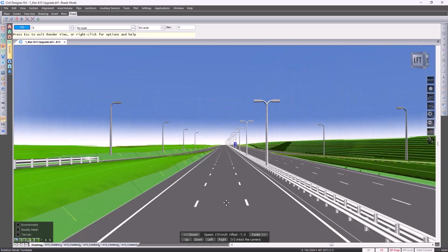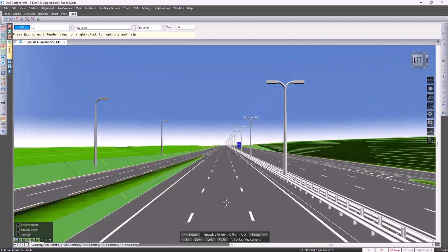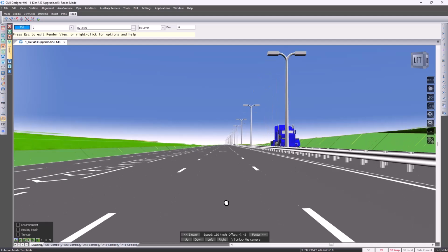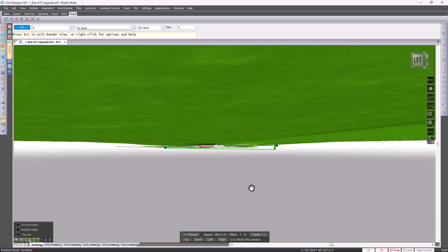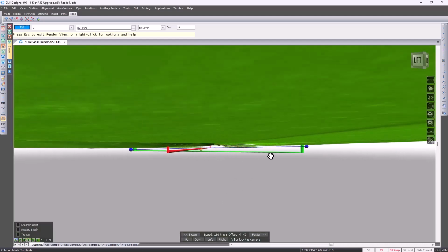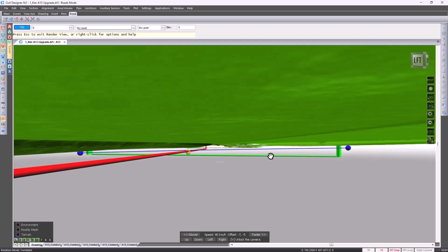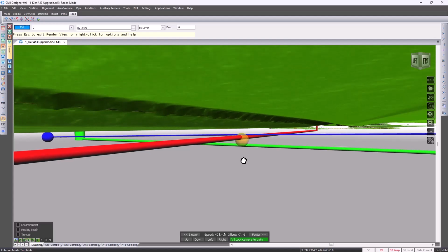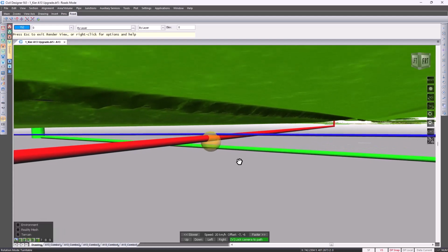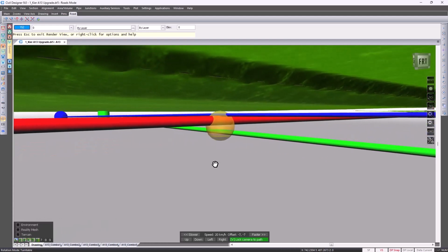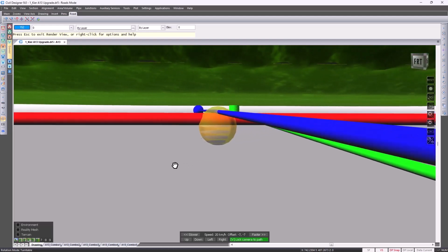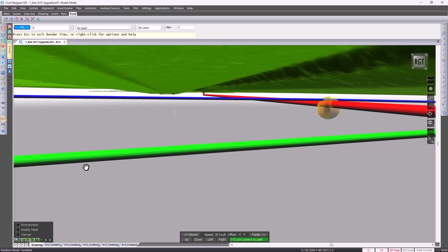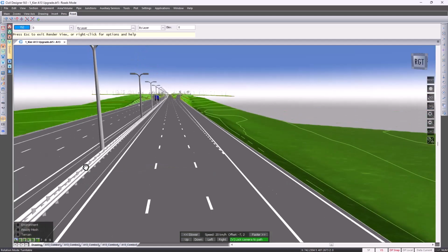You can travel beneath the ground and check for clashes between these different services. And as we approach these pipes, I'm going to slow things down somewhat. If you look at the position of my cursor, eventually you'll find that we've got a yellow balloon. That yellow balloon indicates that we've got clashes between our different services. Not only if they clash, but also if they're within a certain proximity, will Civil Designer point it out for us.